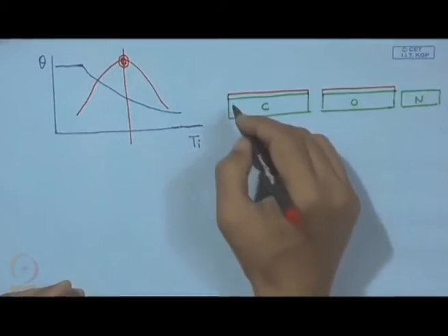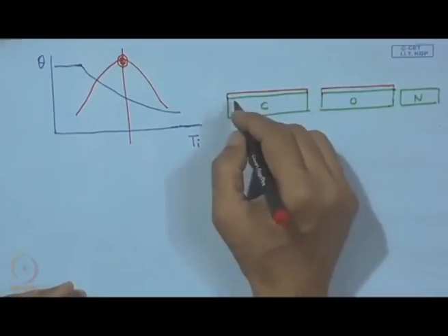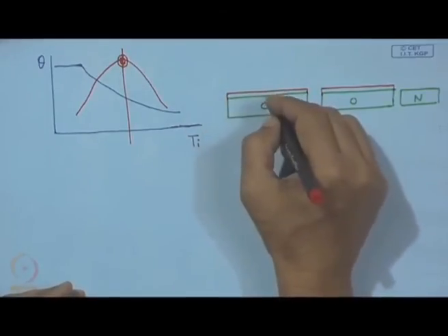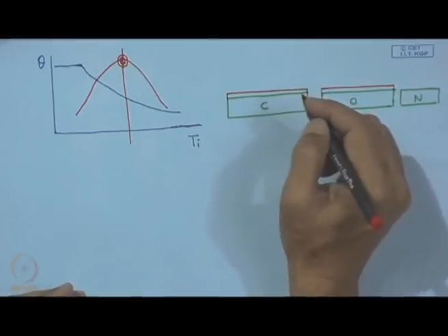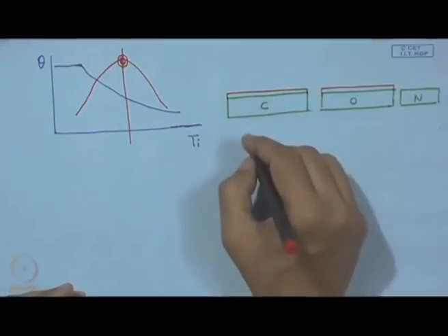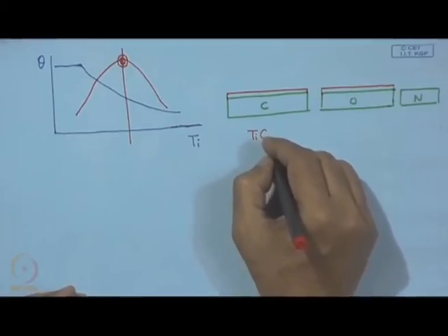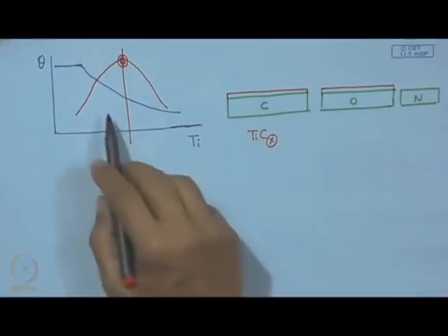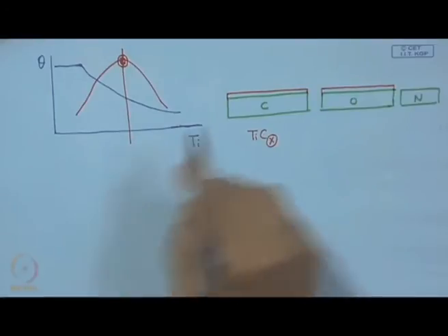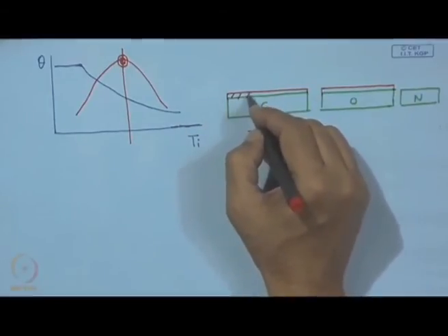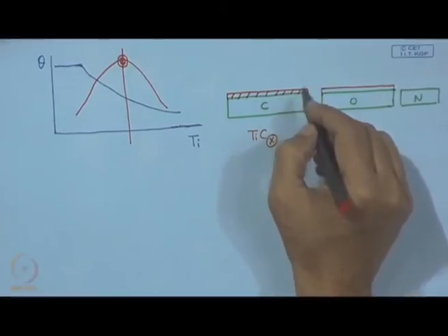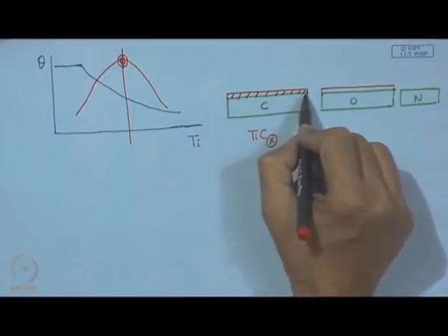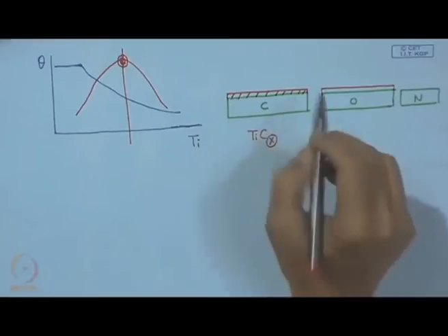This increased amount of titanium thickens the layer and at the same time makes the outer surface richer in titanium. So, the outer surface which is richer in titanium, that means here a very low value of x, and with that we have a still further improved wetting, but that is at the cost of bonding. So, this thick reaction layer no longer supports any externally applied force and the breakage occurs at this interface.